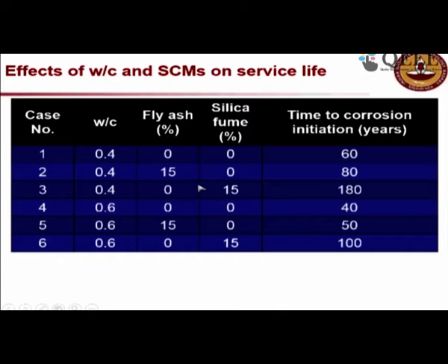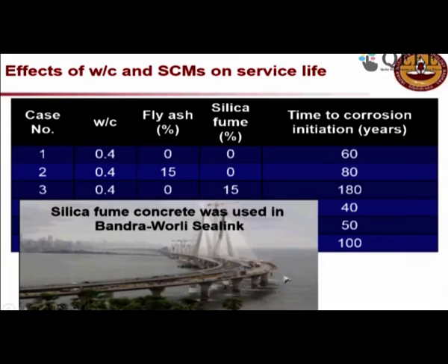And also if you compare the row 1 and row 4, you can see that the time to corrosion initiation is decreasing from 60 to 40. That is a reduction in 20 years when you increase the water cement ratio. So in Bandra Worli Sea Link, they have actually used silica fume concrete to increase the life, because this is right in the ocean, a very aggressive environment. You have a lot of chlorides here. So you have to have a highly impermeable concrete so that the rebars inside are well protected.